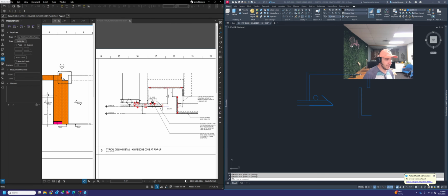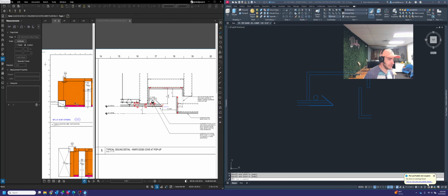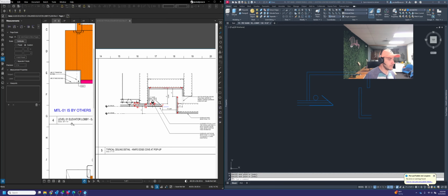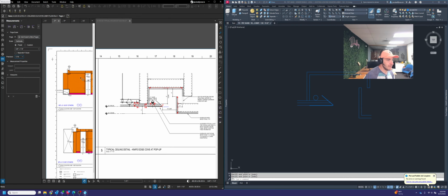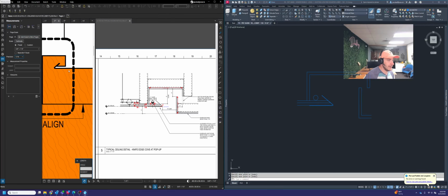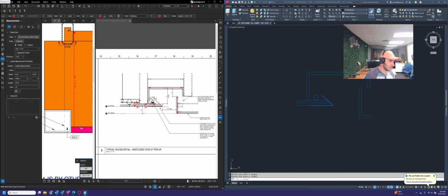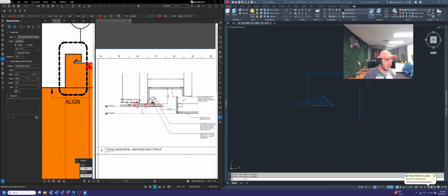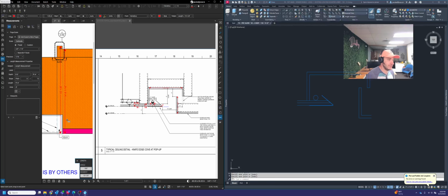So looking at the drawing here, I just want to pull a quick measurement to test something. Changing my scale to match this elevation view, that's 3/8 equals a foot. If I go to that and I pull the scale from there, let's go ahead and see what they have this drawn at from the top of that ceiling to the floor. 14'6", so that's 14.5 feet. And then this is probably the 15. Yeah, okay, that would be about 15.